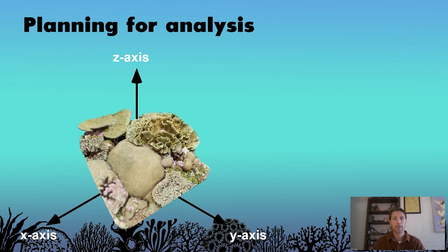Okay, it is now time to move on from the images themselves to the other key pieces of information that you will need to collect as part of your large area imaging surveys. Structure from motion is the technology behind large area imaging, and it works without the need for any external inputs of scale or position. However, in order to be able to extract quantitative information, such as the size of corals, scale and orientation must be provided. Such information can be obtained in a variety of manners.